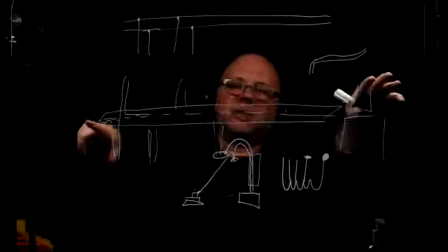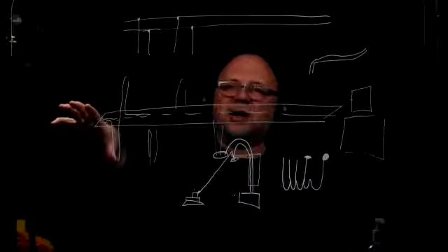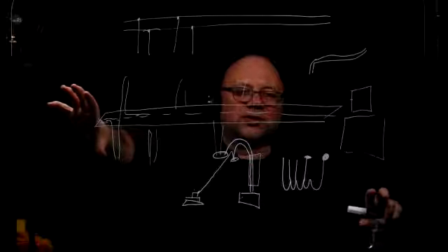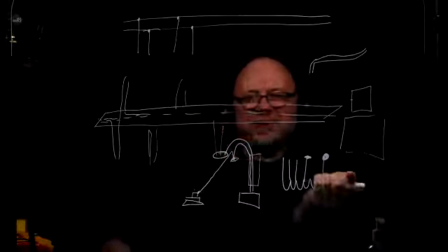Plus, if it's a bigger amplifier, the speaker is going to start working too hard, and yeah, it's going to get damaged. Right? If it's a smaller amplifier, here's the other thing. If this is a 100-watt speaker, and you're just going to put a 10-watt amplifier, is that okay? Still not okay. Because you can crank the amplifier full blast to the point that it's going to start distorting.